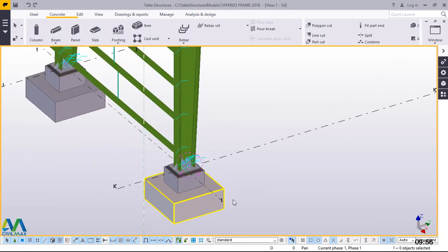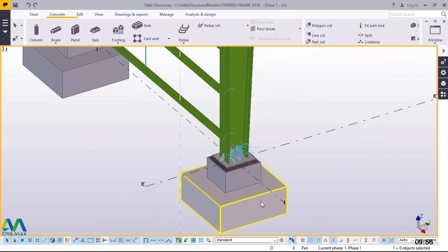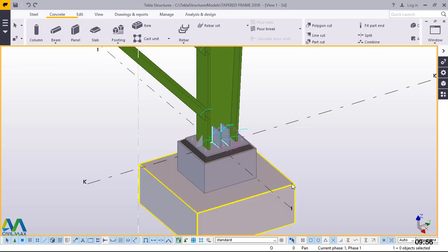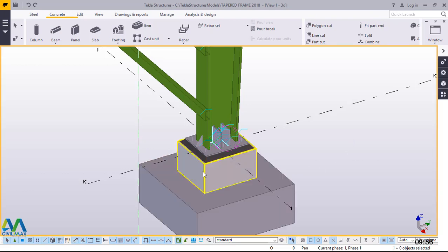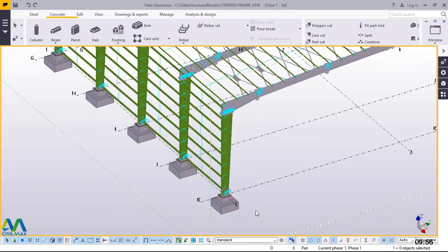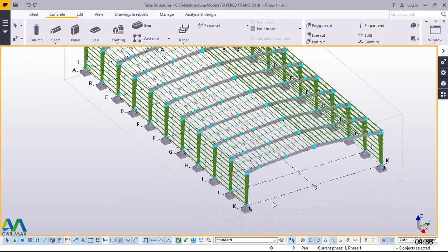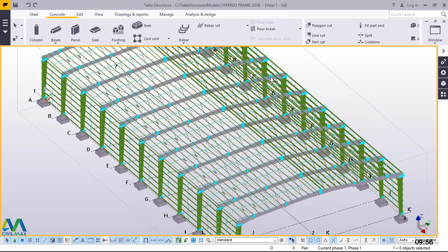That was just a brief explanation of how to place this. And maybe you want to, here you'll realize the moment I press Alt and click on this, everything will be selected. What I did, I just combined the two to be in one assembly, or in one cast unit. Now we are going straight to drawing creation, and we are going to use the templates in the master drawing catalog.